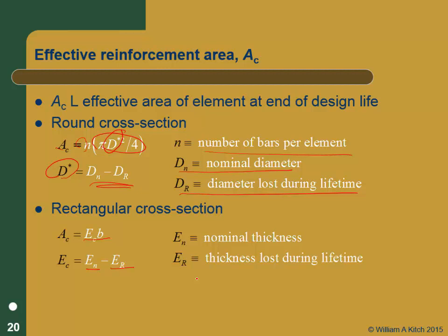Essentially, whenever we do our capacity calculations for the reinforcement, we're going to estimate how much reinforcement is actually going to be there at the end of the life of our structure, and we're going to design for that area.